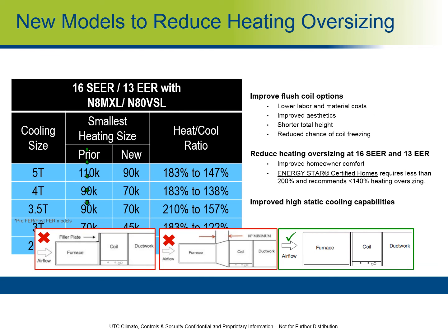All right, some of the newer models actually have newer size and tonnage ratings to help eliminate oversizing of heating. So on the 13 and 16 SEER products, you can still attain your airflow on a 5-ton unit.